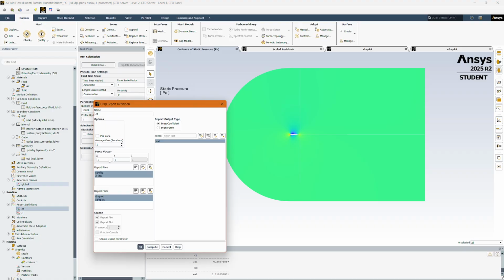And then the important thing before we continue is we have to change our CD values. Because if we're taking CD as if the velocity was coming along the body, we'll get very wrong values. So I'll change this over to, for drag, 0.9848. And for our Y, we get 0.1736. And this was just found using our angle of attack.